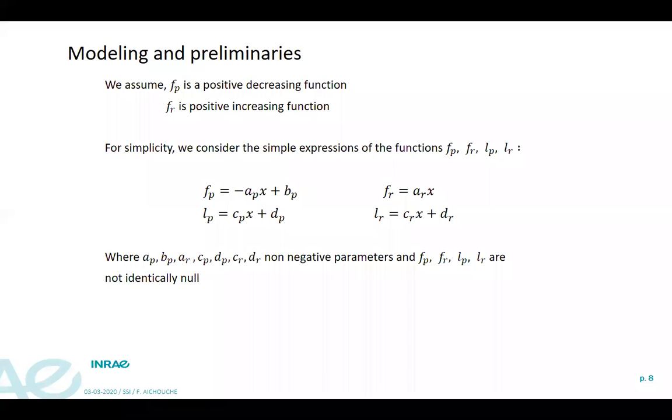So, when the membrane operates in the filtration, the flow resistance increases according to the mass x formed, which subsequently decreases the permeate flux. We assume that the rate Fp is a positive decreasing function. When changing to backwash, the mass is decomposed and the membrane's permeability increases again.